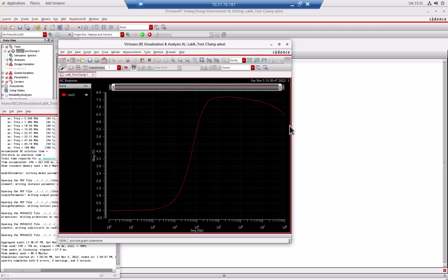Do you know why? Yeah, think about that, right? We have learned about the biasing before. For the high frequency part, it's just because the transistor capacitors start to play a role. That's why you have a pole, and then you start dropping off, right? But for low frequency, why is it that it has a low gain, right?